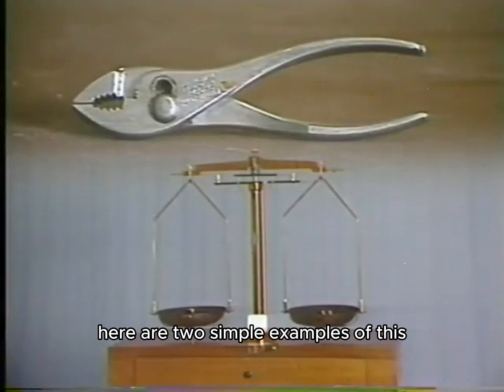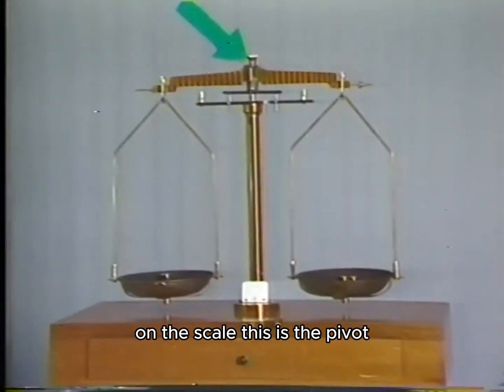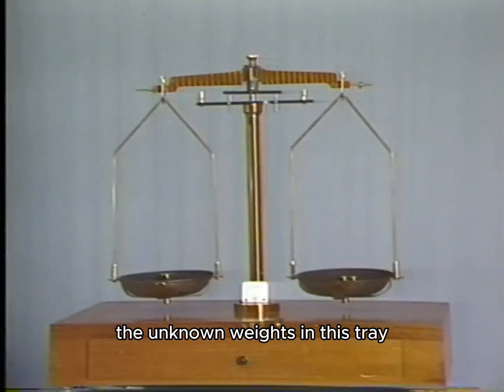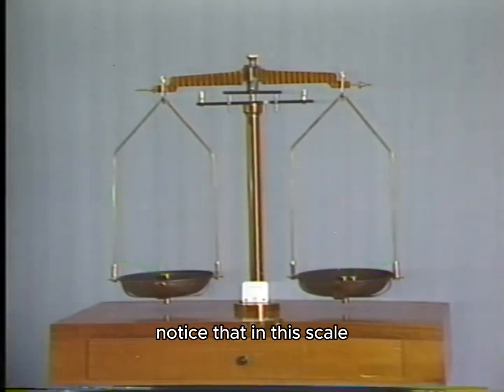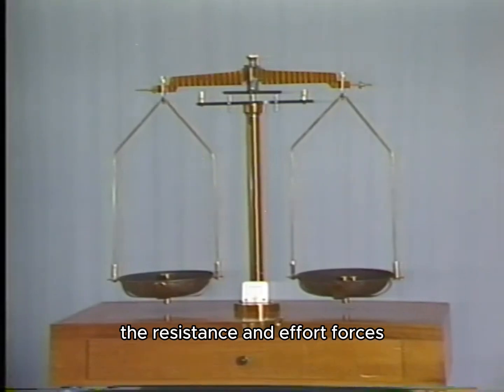Here are two simple examples of this first group of levers. On this scale, this is the pivot, and this is the lever, which I referred to earlier as a balance beam. The resistance force is the unknown weights in this tray, and the effort force is the known weights in this tray. Notice that in this scale, the pivot is centered exactly between the resistance and effort forces.